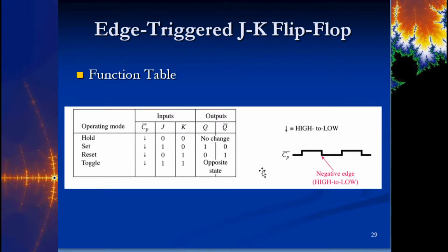What if you could chop that down, divide it by 2, and then when we learn counters later, you can divide by whatever number you want. So let's say we divide that number by 6 to get it down to 10 hertz, right? Then we take a divide by 10 counter and knock that down to 1 hertz. Now we've essentially got a free power supply coming out of the outlet.